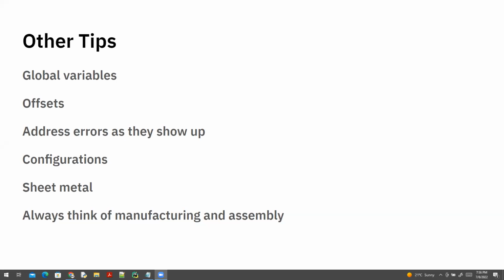But when we're talking about the bending, it doesn't need to be complex. Sam mentioned just using a vise. With some of the stuff, you can print off the diagram and use some glue to put it on the part, that way you can mark where the line is and stick it in the vise and just bend it over. It's pretty amazing how accurate you can get using that technique, but don't try to do it during build season. Do it in the off season so that you know that you can do it. And that just makes it a bit easier.